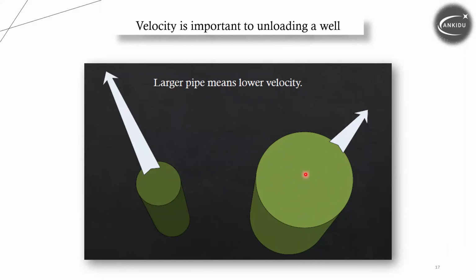Do we put the tubing only, annulus only? What is the size? The larger diameter for our pipe means lower velocity, and lower velocity means we don't have a successful restart of the wells, because we don't have enough speed to bring the flow again from the reservoir inside the wellbore to the surface. So we have to consider what the criteria of the diameter is.